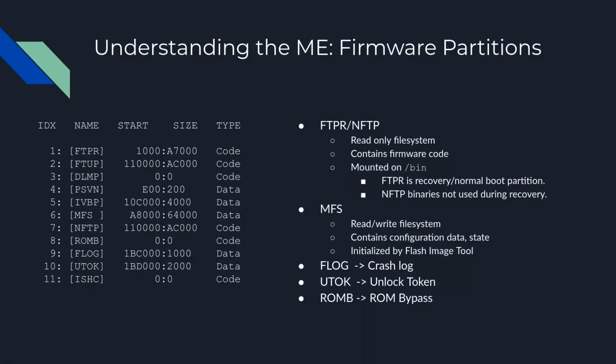Like I said, you can't get access to the ROM without running code on it. And the ROM is mask ROM, so it's internal to the chip. But Intel has to develop new ROM code, and they have to test it without respinning the die every time. So they have the possibility, on an unlocked pre-production chipset, to completely bypass the internal ROM and load even the early boot code from the flash chip. Some of these images have leaked, and you can use them to get a look at the ROM code even without being able to dump it. It's going to be really useful later on.